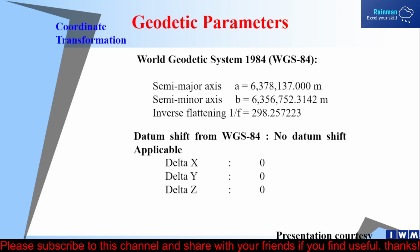So you have to have a clear conception about the datum or geodetic datum. So what is datum actually? Datum is a reference line from where a particular point is measured, or the height is measured. Let's say mean sea level is a datum, and from that mean sea level, for any point on the earth, the elevation is measured, the vertical distance of that point from the reference line, that means level, is called the datum. It's the datum.